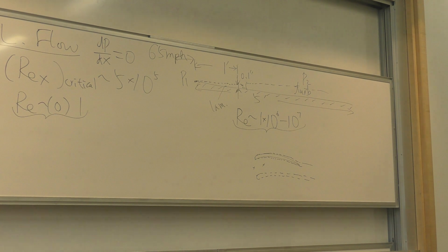There was a question in the back? Yes. For something like a ship where you have it going through air and through water, how does... So for a ship, you think about the physics, right? You should know how much the viscosity of water is compared to the viscosity of air. Water is much higher, so all you care about is the wetted surface of the ship, right? The shear it creates, which is what we call the frictional drag, and also the form drag, the wake created by the ship when it passes, pressure is lower, and the difference between the pressure up front and the back creates another drag. What kind of drag do we call that?